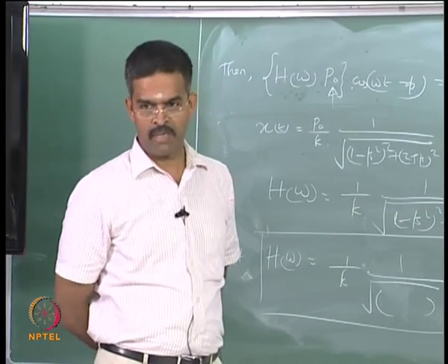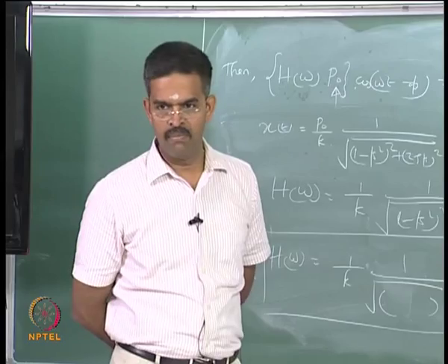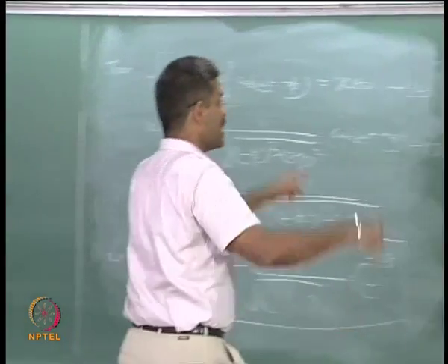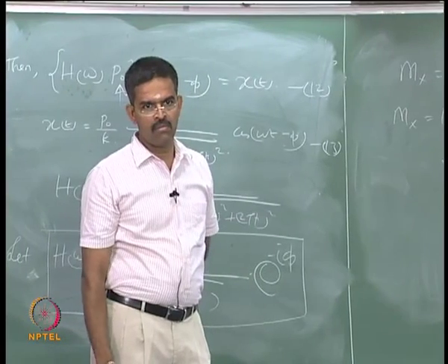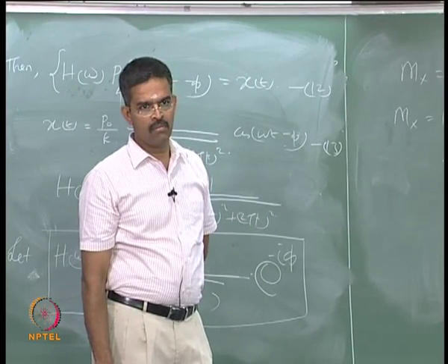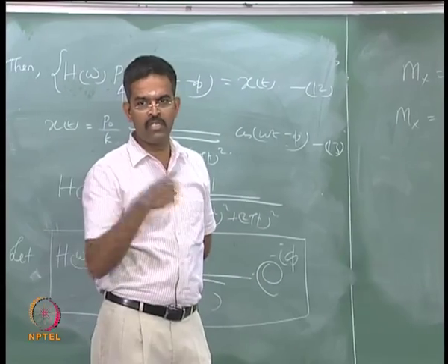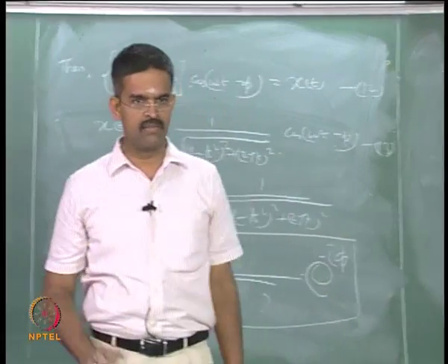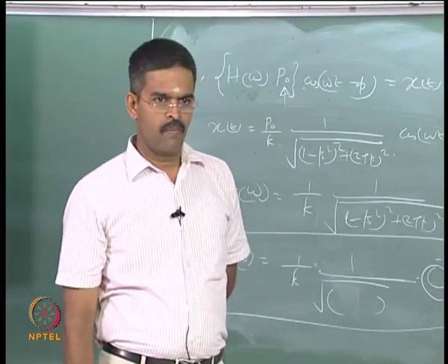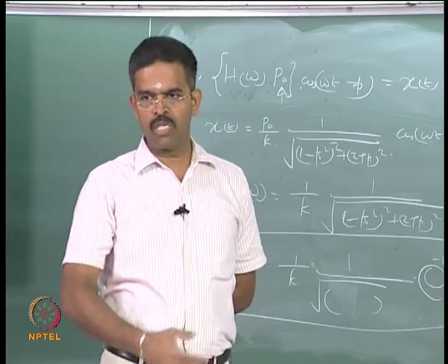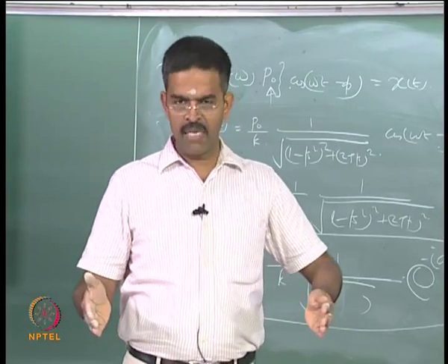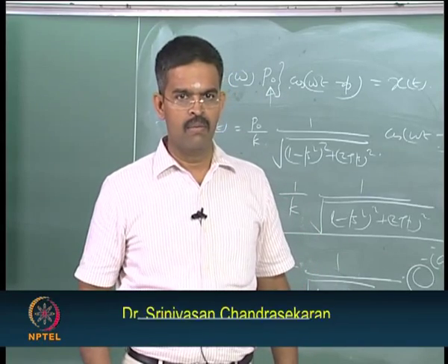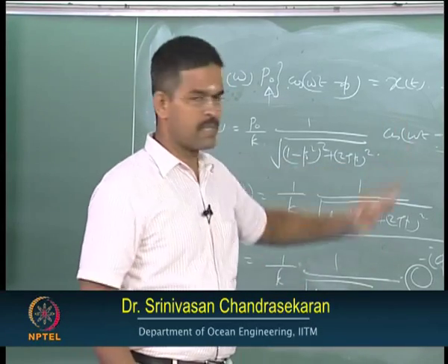So, if you know the response spectrum for any given system, you can always characterize the system for any load. Therefore, we can design the system. Okay, that is what the catch is. Okay, somebody gives you a response spectrum, you want to check the system, is it safe for a specific bandwidth of omega, and the load spectrum is given to you.